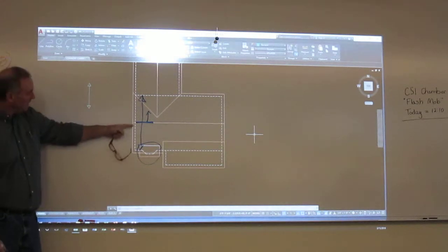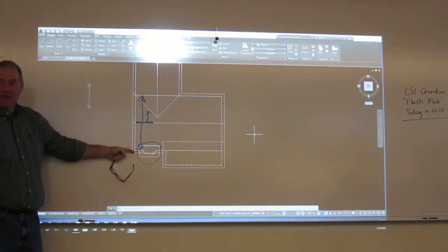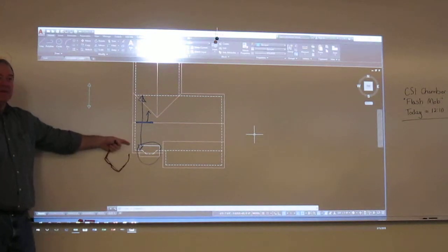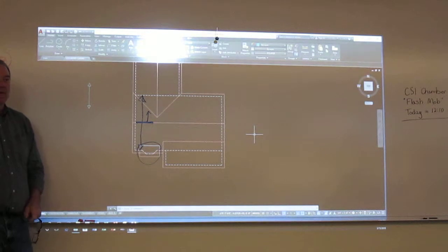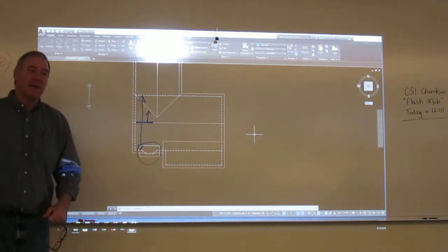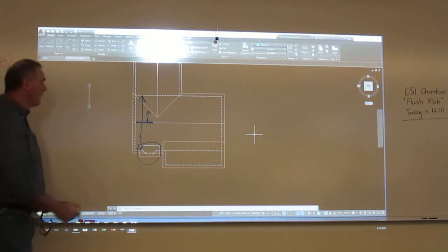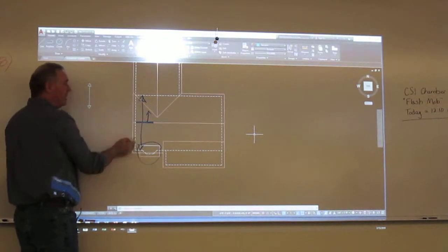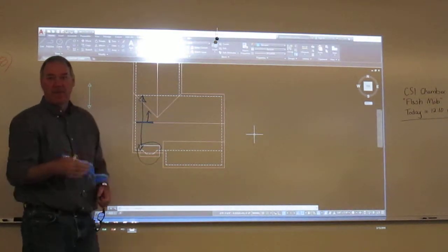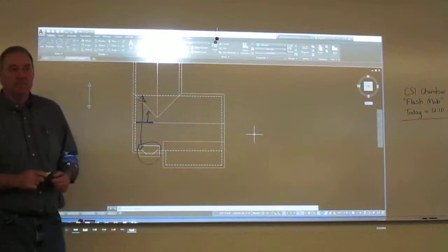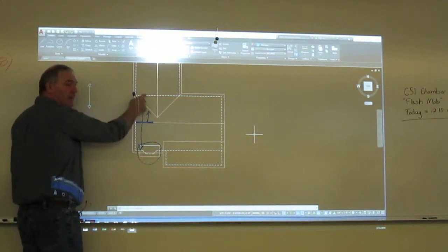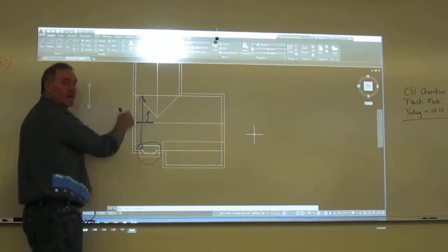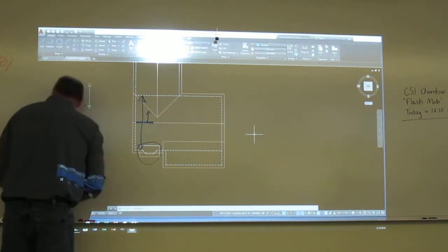Now I'm going to vault my master room though. What kind of shape is this one? If you look at page 718, it's a gable truss, right? We still have a gable end here, it's a gable shape on the outside. What's going on the underside? We're not vaulting from bearing to bearing, that would be a vaulted truss. We're just doing a section of it, so it's a scissor.